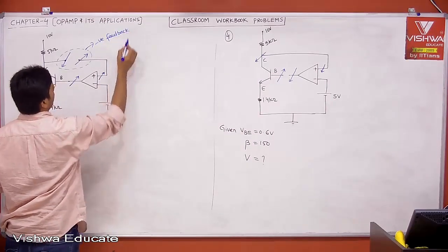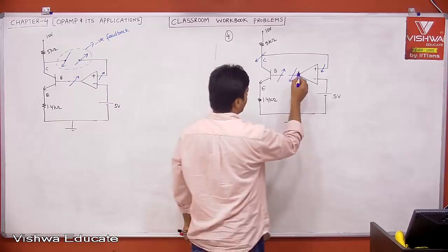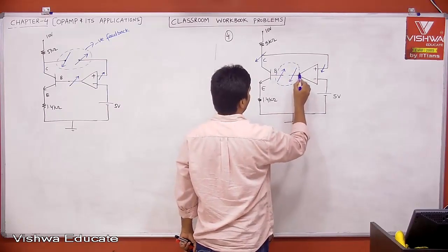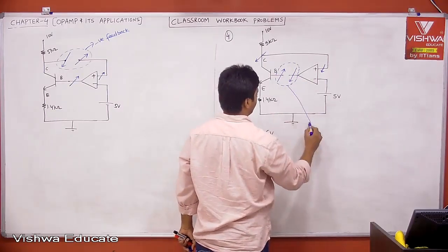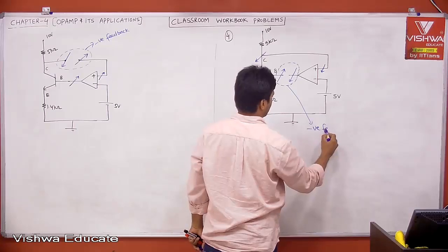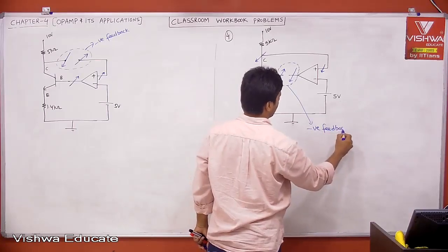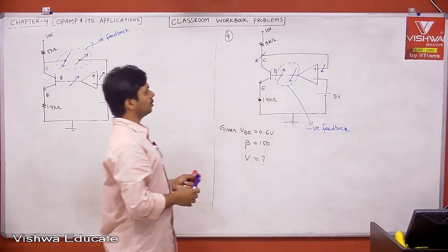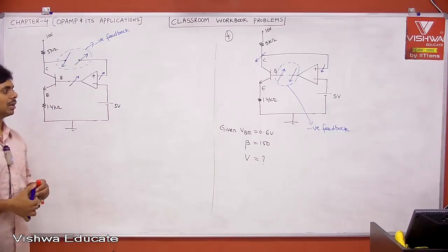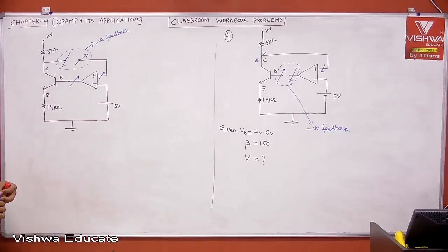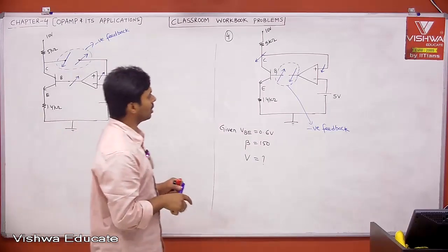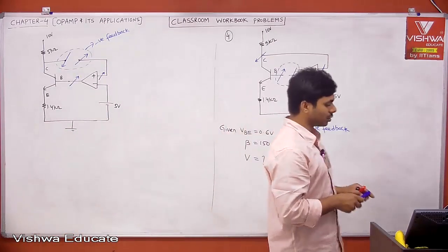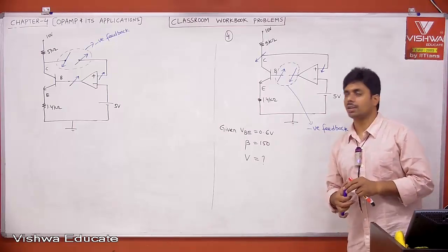Did you understand the technique? Therefore, from this also, wherever you have the loop, remember, you can open the loop and then change, then you come back. If the change is opposite, negative feedback. If the change is in the same direction, then positive feedback. Okay? Therefore, one part is over, finding the feedback. Now we got to know that it is in negative feedback.